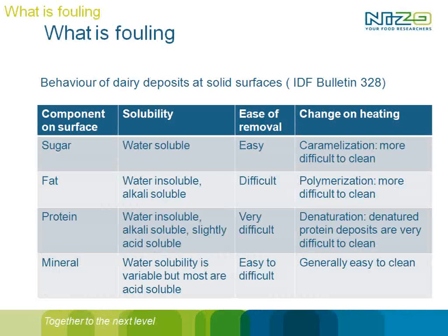Okay, so far NIZO. Now we go back to the webinar about fouling and about cleaning in place. And first of all, as we said, know your enemy: it's important what fouling is exactly, so what type of fouling is going around in your equipment. We made this overview table in which we have four different types of fouling, looking at the more protein and mineral fouling.